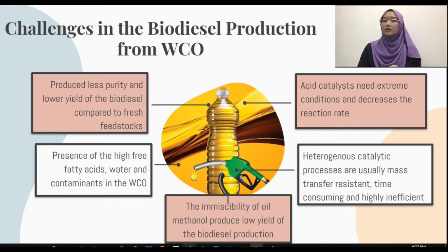The presence of water and free fatty acid also makes them unsuitable for homogeneous alkaline trans-esterification catalysis because the alkaline catalyzed reaction is highly sensitive to them. Next, the challenge in this transformation is the immiscibility of the oil and methanol, which can produce a low yield of biodiesel. In order to overcome this problem, the mixing efficiency should be improved. And also, in this transformation, the usage of the catalyst in this process can affect the production of the biodiesel.